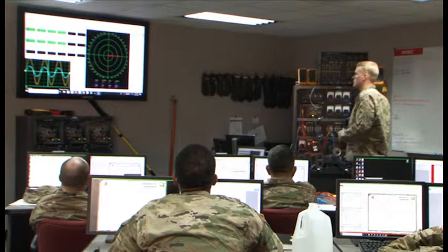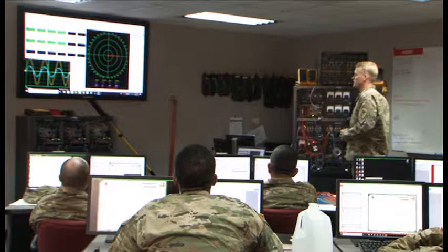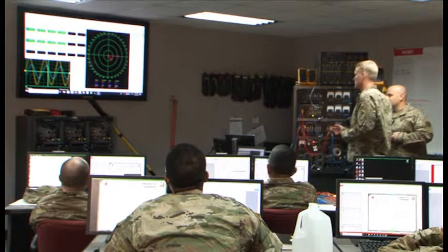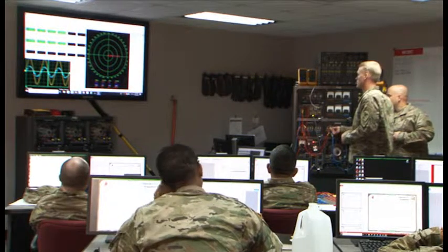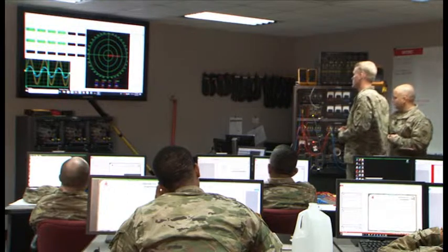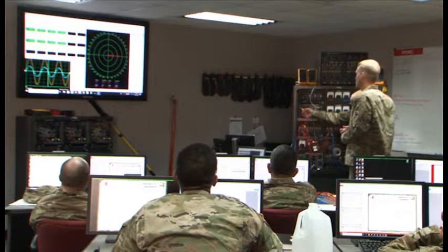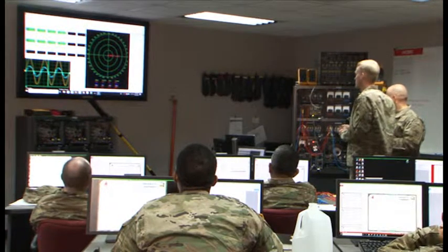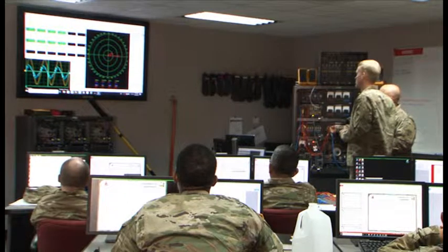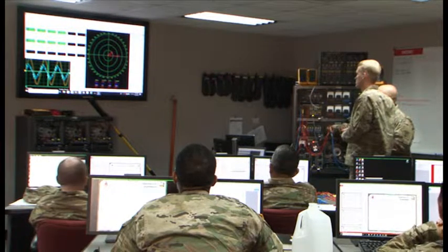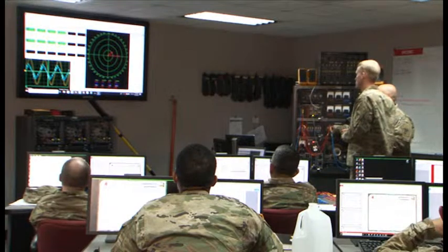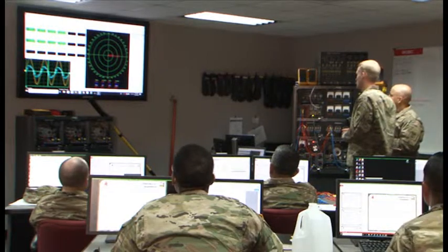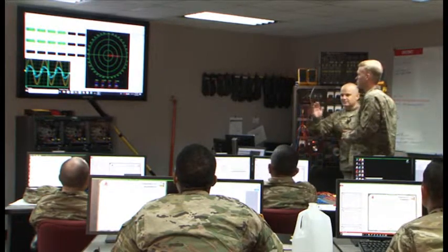Is that what's expected? Yes. And now flip off this one, right? I'll flip up. And we're seeing that jump back and forth, right? Now pay attention to those vectors that you're seeing up to the reference vector, because we have it referenced off source right now, right? Everything's off source, okay? So is our source voltage changing as a result of this? No. I mean, in the grand scheme of things, the source voltage was the source voltage. Well, what is changing, though, is the current. All right, and you can see those minute shifts in the magnitude of that current vector.